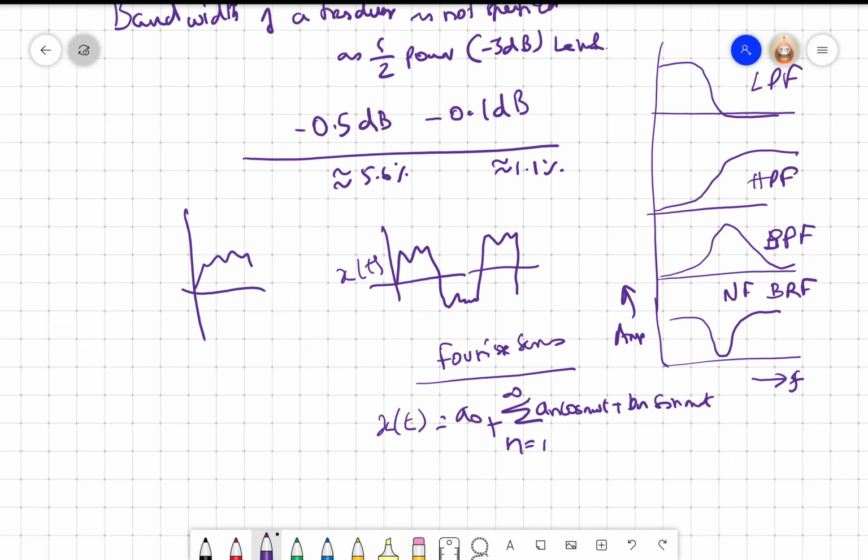So I can now split my input into a series of sinusoids and then find out for each sinusoid what would be my transducer output, add again, and I will get the response for this, right? Of course, if it is aperiodic, I can use the Fourier transform and get the frequency response characteristic, something like that. This is frequency, this is amplitude, right?